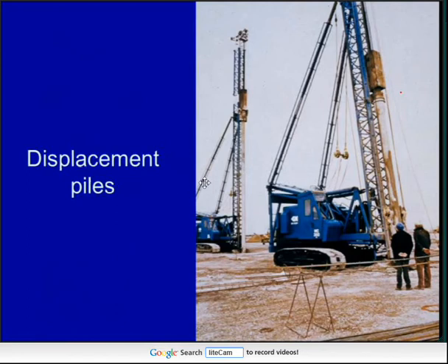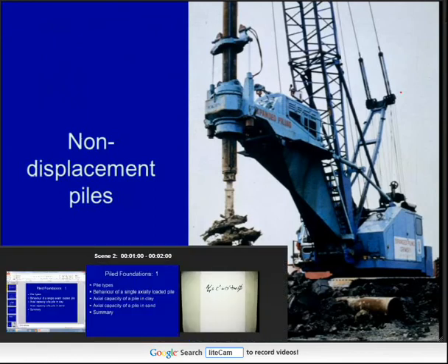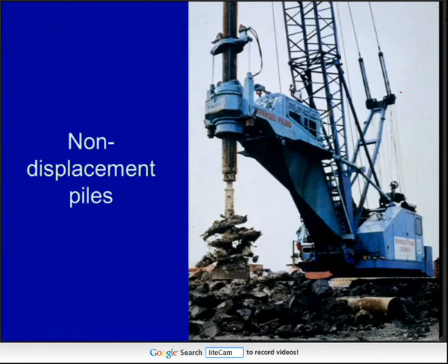The other type of pile we have is a bored pile. It's very hard to show the roughness of that hole on a piece of paper. I'll sketch it on the paper for reference later. But the roughness of the hole you'll get from that is literally that sort of level of roughness. Great clods of soil. You can see them being ripped out of the ground by the auger. The diameter we use in design for an augered pile is the diameter of the pile itself, because we're guaranteed to have that diameter all the way down the hole, but locally the diameter can be significantly higher.